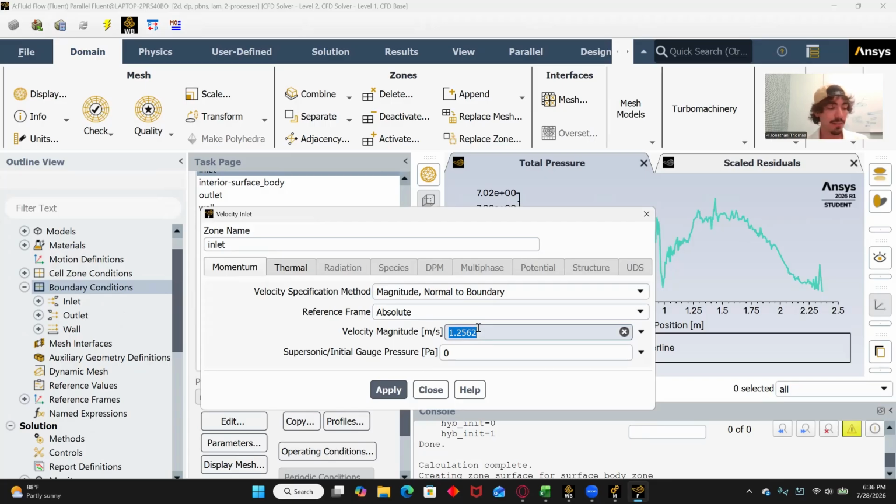So we use AV equals AV. And since it's 2D, again, we don't use area, we use the height. So multiplying that number by 6, which is the test section height, and dividing by 22, which is our contraction chamber height, we end up getting 2.6139. So that's our inlet velocity for 40 hertz.